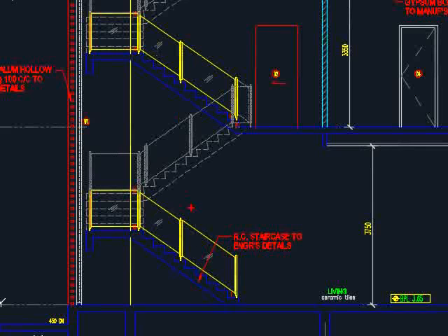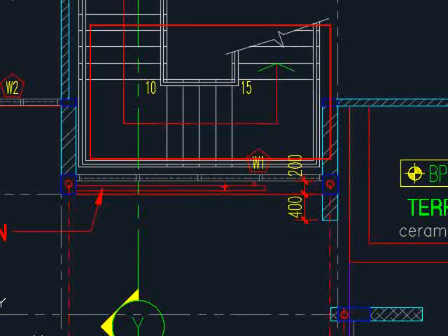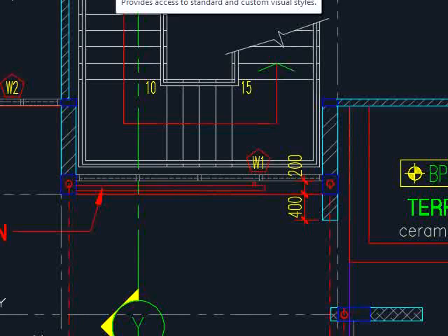In this case, the staircase seems to be a cantilever staircase. It is for you to decide whether you want to make it cantilever or whether you need columns along this side of the staircase. This you will need to check from the view of the building. You know that the staircase is in front of the windows, and these windows are to be installed onto the column here. You will need to decide the positions of the column if you really need the columns for the design. Most likely you're going to put an additional column here to support the landing beam.